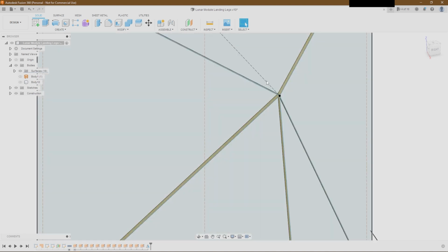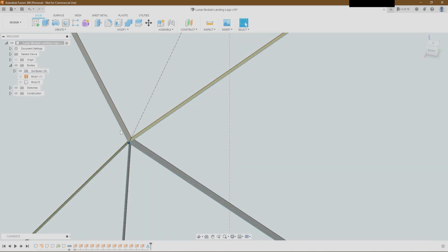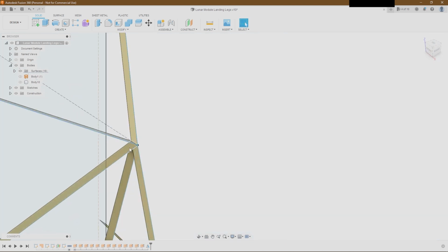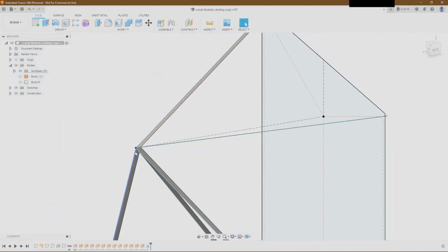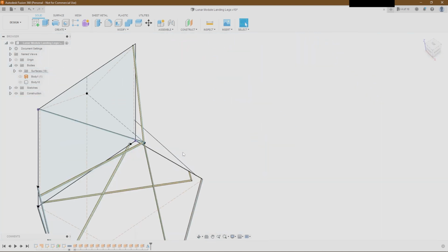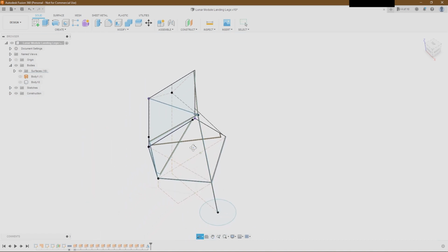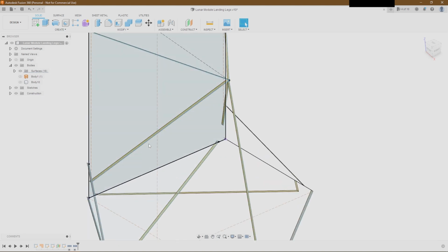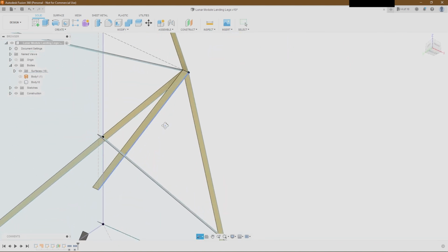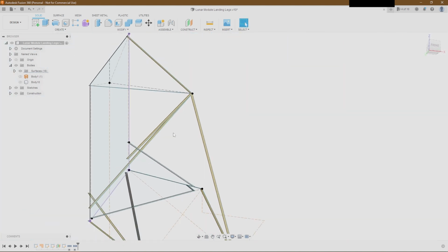So the surface now has a curve right on the front edge that I extruded from. So we just use that front edge in the analysis, and you'll see what I mean if that doesn't make a ton of sense. So this step to make all these little 1-inch surfaces is just because I'm using Fusion.